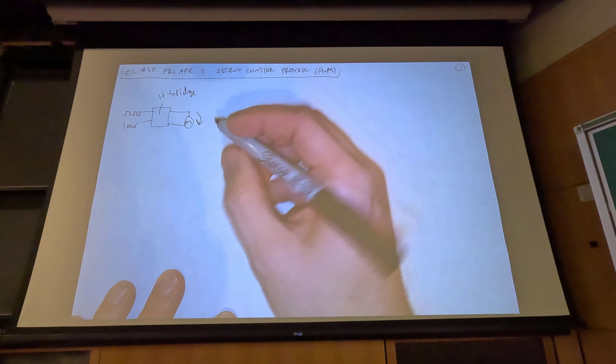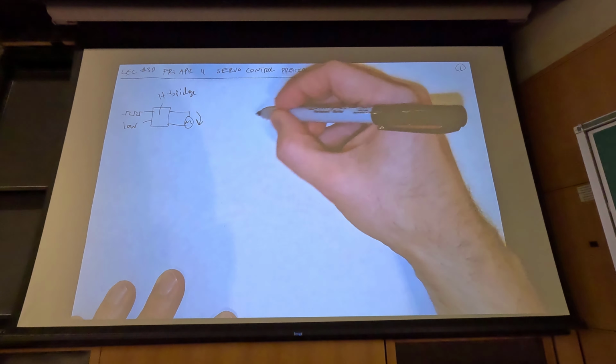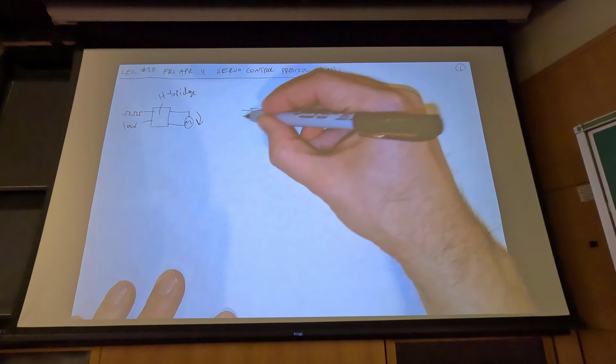Same idea here. If we send a PWM signal to one, and just set the other one low, the motor will spin one way. And if I want to spin at partial speed in the other direction, then I need to send a PWM signal to the other pin. Okay, so if I only care about controlling my speed when I'm driving forward and not when I'm driving backward, then you don't necessarily need the PWM signal on that other pin. This one can just be digital, purely high or low.